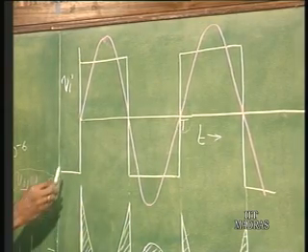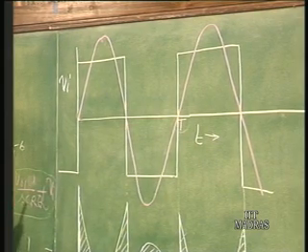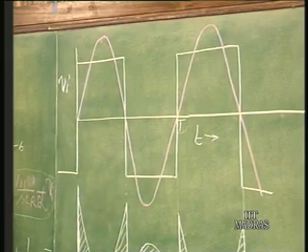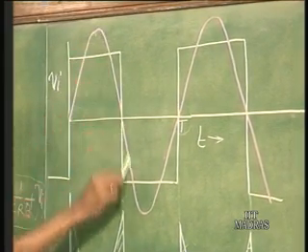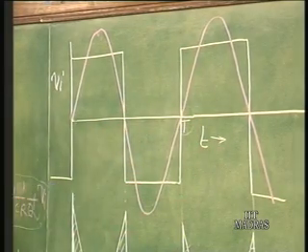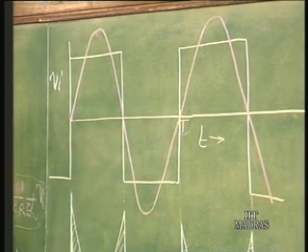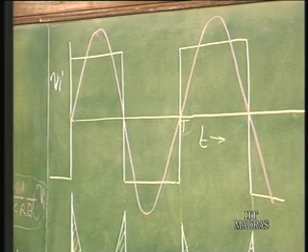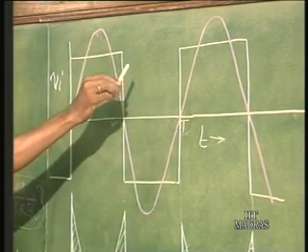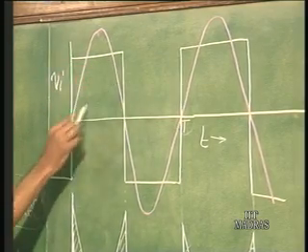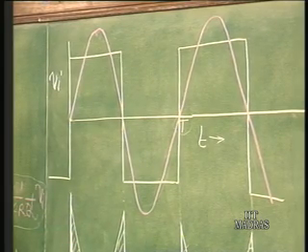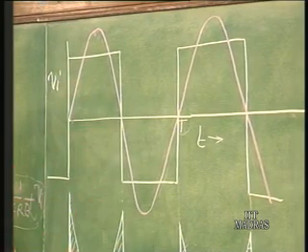Okay. And if it is exactly tuned to omega naught, if the incoming frequency is the same as omega naught, which is equal to 1 over RC of the filter, then at the band pass output it should give me the fundamental. You should select the fundamental and eliminate all the harmonics. So, this may be some kind of fundamental output. And it will be almost Q times the input. So, the fundamental amplitude will be very huge. If I apply some value of input signal, Q times that is going to be the fundamental output, compared to the fundamental of the input square wave.